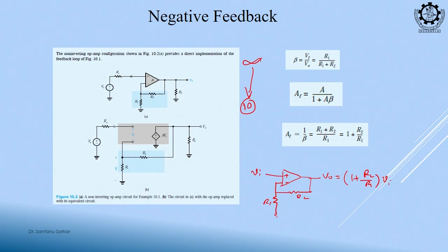Right. Now, my question is, why did you design an op amp, why did you take the pain to design an op amp with a gain of infinite, meaning very large gain? You are using a very finite gain and that is not that large. Why do you take the pain to design an amplifier with very high gain? Can you answer me? Is the question clear? Control the gain, which gain? Closed loop gain. What will happen if A is not infinite or A is not large?